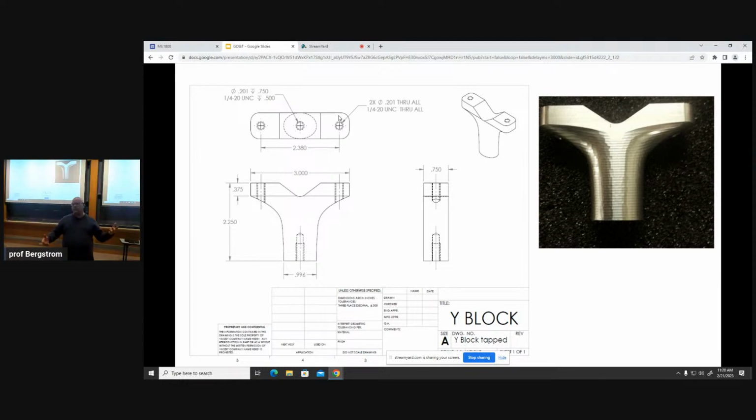So, well, I probably want to dimension them from the center line. Ideally, I'd like to be at the center. But to pick how much off the center line is acceptable to me, what do I have to know? I need 2 pieces of information. Because we buy the clamps, we're not making the clamps. I need to know what's the width of the clamp and compare that width to the width of the whole thing. So how much allowance do I have? How much could I possibly move it back and forth and have it not overhang the edge? And I need to know what the diameter of the holes inside is. Right? But mostly I need to know that width.